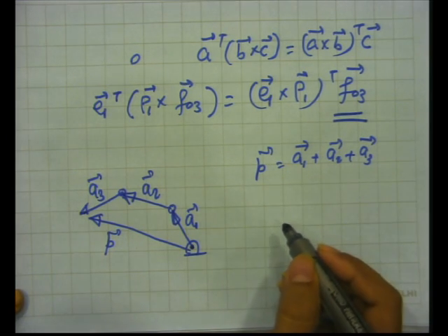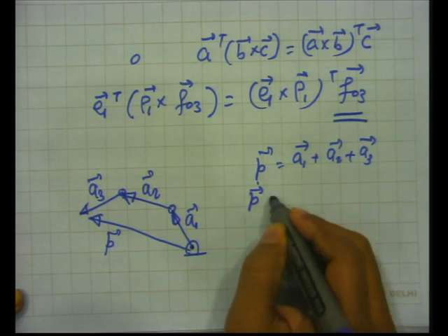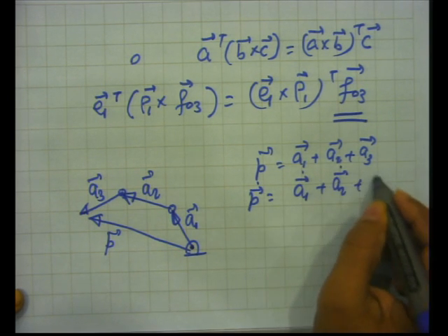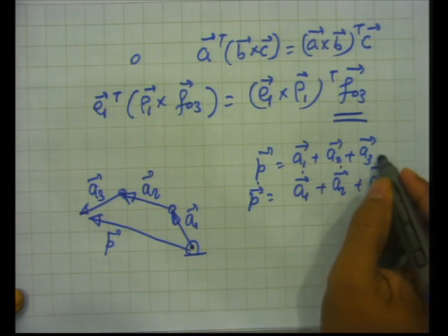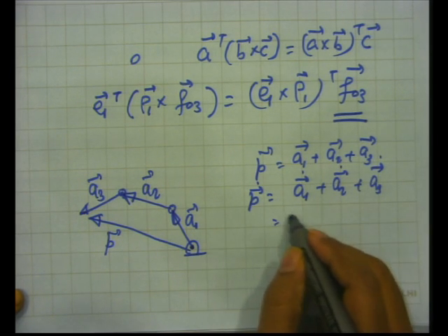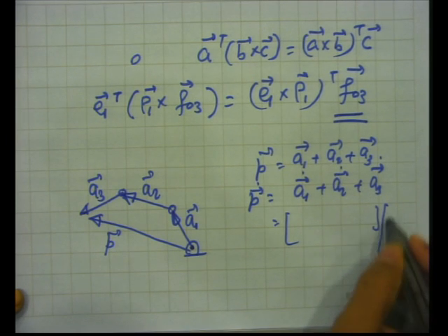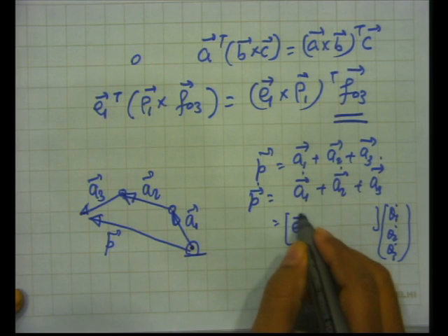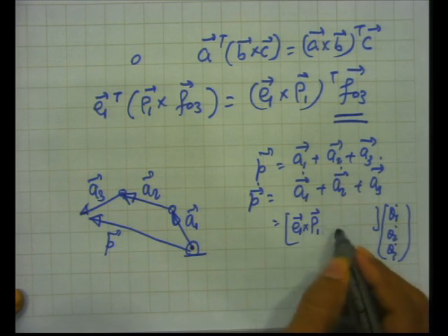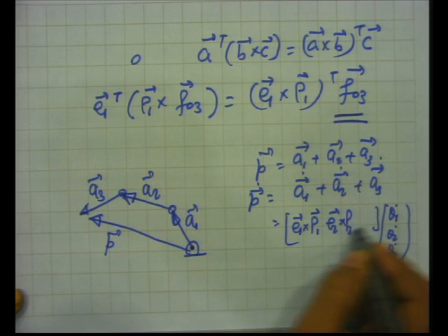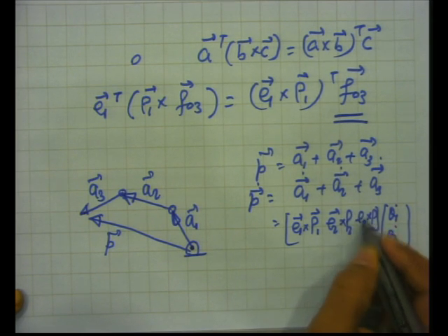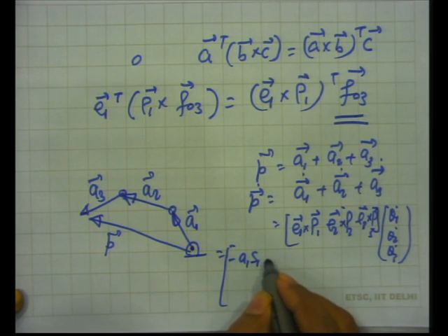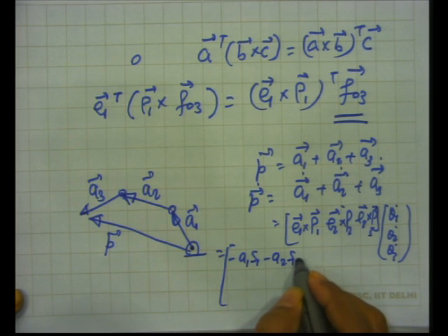In classical Jacobian definition, I know the P dot will be A1 dot plus A2 dot plus A3 dot. Okay. And if you do all these derivations, you can find out that this expression, writing in terms of theta 1 dot, theta 2 dot, theta 3 dot, will be nothing but E1 cross rho 1, E2 cross rho 2 and E3 cross rho 3. A little clumsy here, but I can calculate for you A1 sin 1 minus A2 sin 1 2.